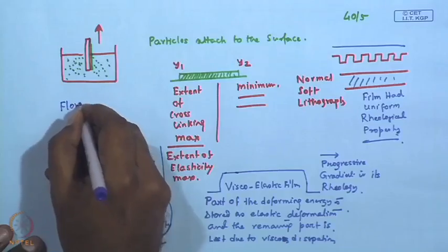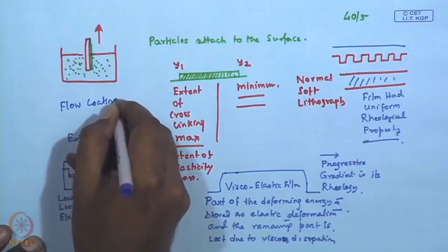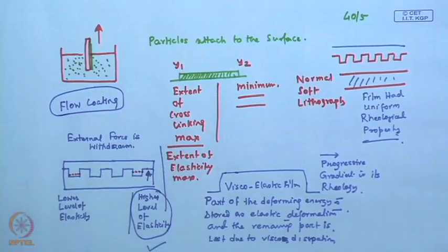Some of the methods which are reported require sophisticated instruments like controlled exposure. There is a very popular method called flow coating, which you can have a look at. It is a flow coater which comes with a stylus and a doctor's blade, and it allows you to fabricate films with different thickness at different locations. A very versatile method, very simple, but it allows you to make gradients.